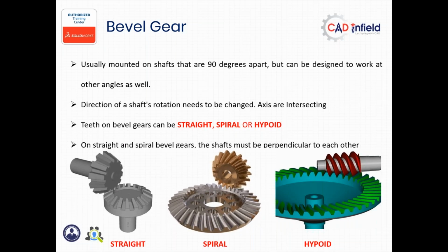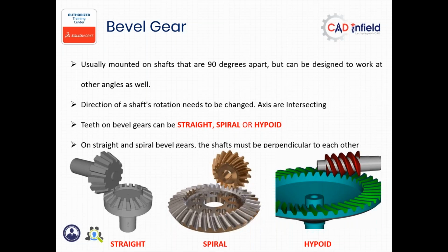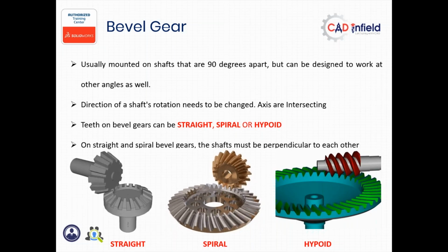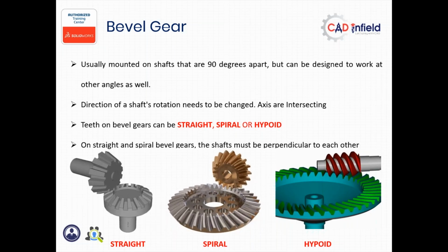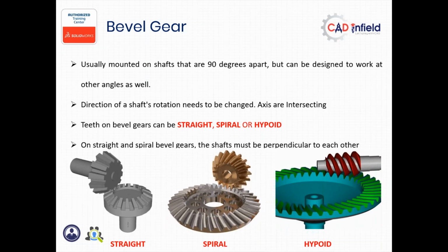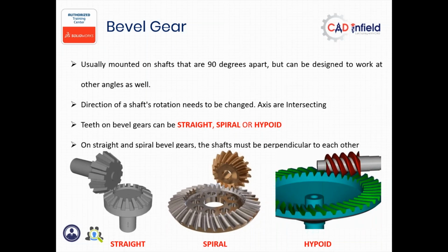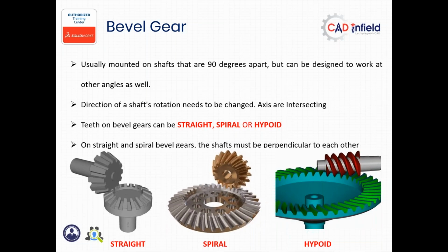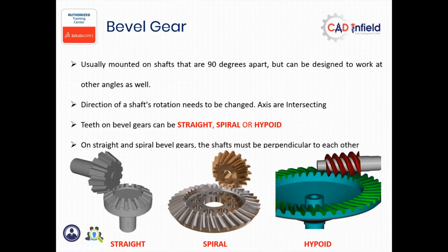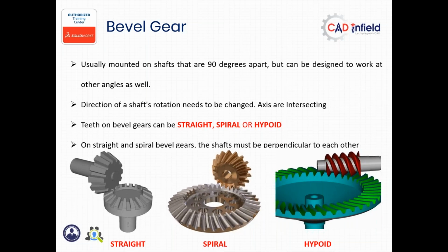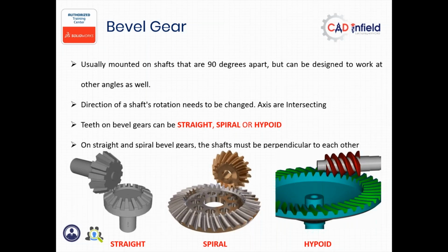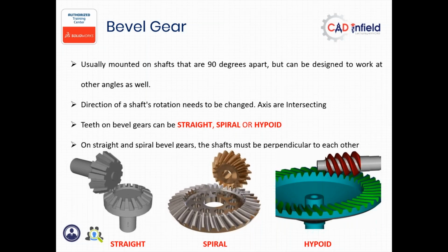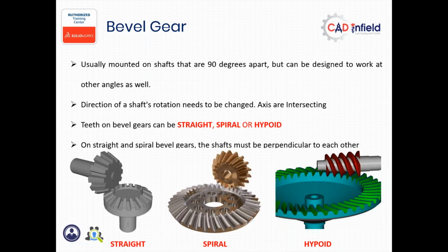This is also very important when we require a transfer of power at 90 degrees. Because we have a belt, we have a chain, and sometimes we have a coupling, which gives an inclination to the power transfer. But if we have a requirement for 90-degree power transmission, then this is the perfect criterion where you can usually select the bevel gearbox.